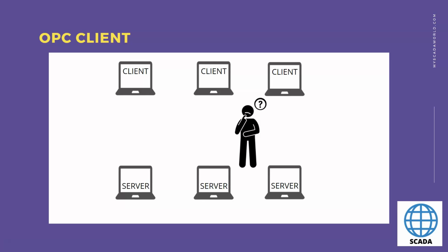Since the OPC server implements the predefined interfaces of the OPC standard, each client can access any OPC server and exchange data with the server in the same way, because it's standardized.